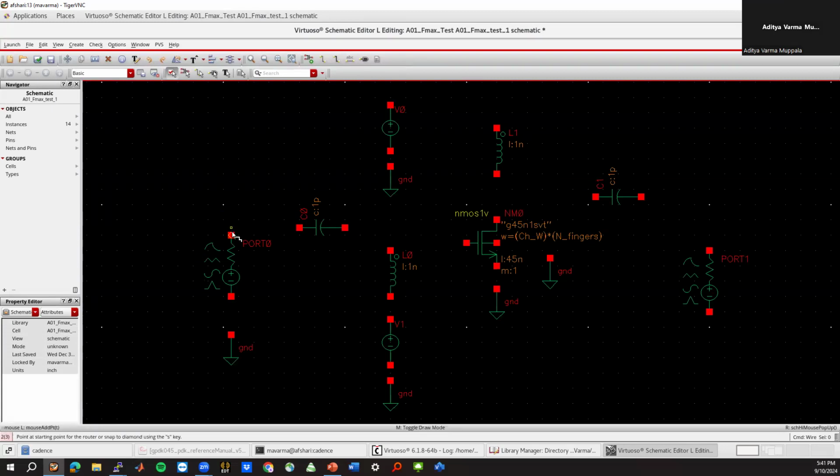But W creates a wire. So make these connections. Click there and then click here to make a U-turn. Click this, click this. I'm grounding the body contact. Okay, and then I hit C, click on that, and then click there.